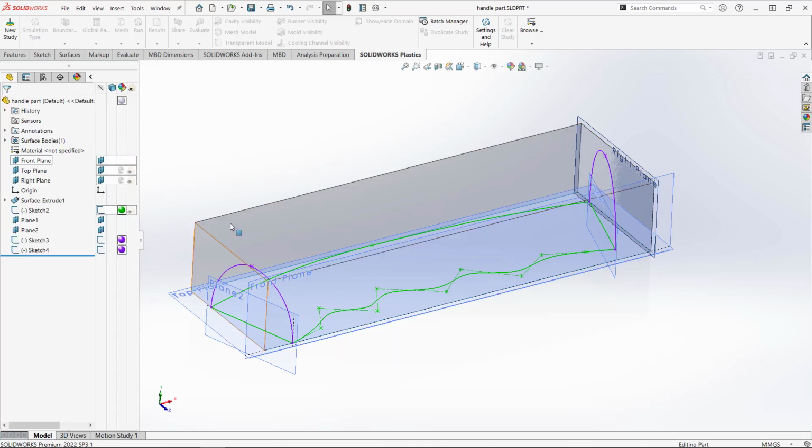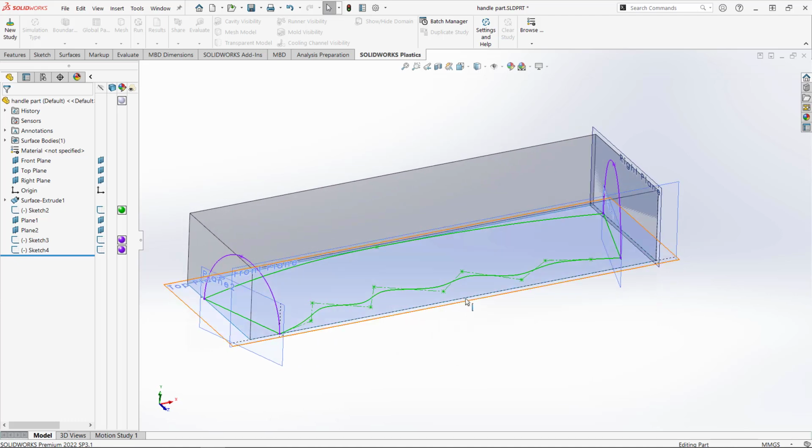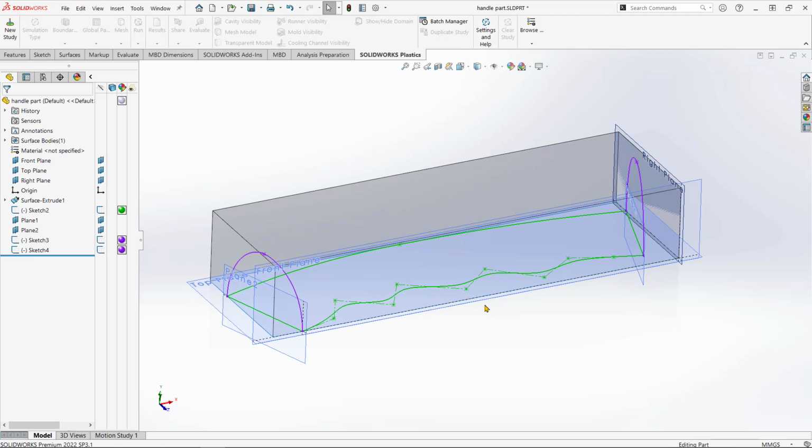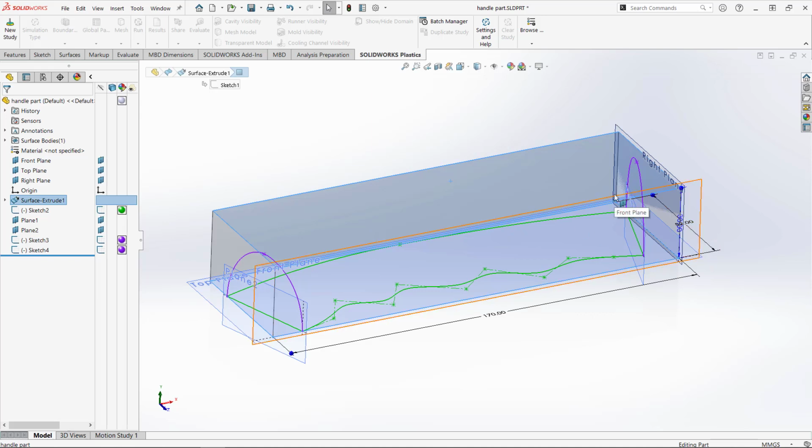And then I exit the color editing menu there. So at this point I'm ready to create my lofted surface. One thing I will do before I begin the lofted surface is I want to hide the limit box that we created, that was the outer limits of our actual part design. So I don't have a need to see that anymore.